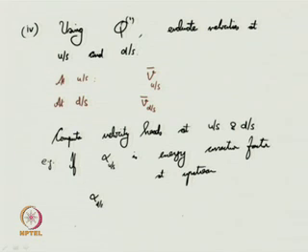Similarly, alpha ds is the energy correction factor at downstream. So, if you have these data, then you can easily evaluate. At the upstream section, the velocity head will now be alpha us v us squared by 2g.